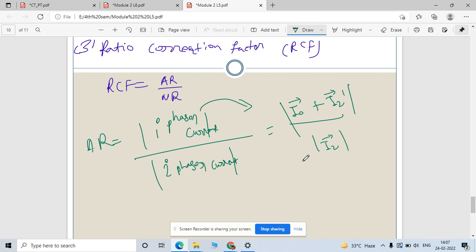Now, what is the concept here is, if you see this I2 dash, this is your main flux, right? This is a reference. Take this as your reference. If I consider in this question, we consider this I mu is equal to your I naught. Okay, and this is leading by 90 degree.